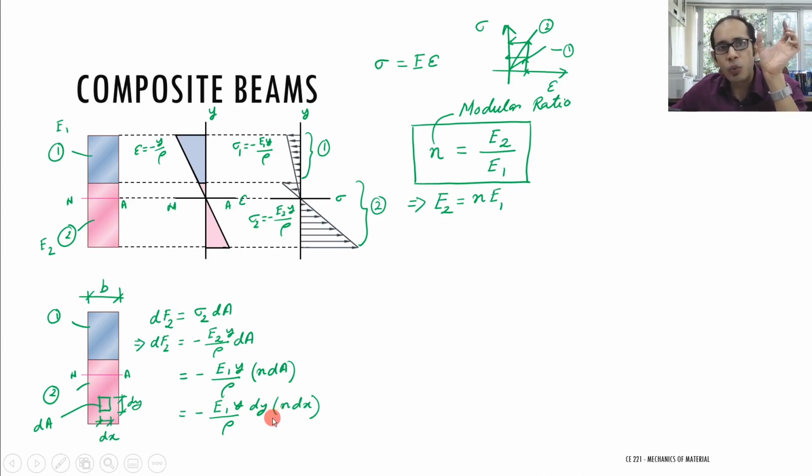Now why am I averse to increasing the height? Because I don't want the position of my neutral axis or the overall strain profile to change. I want it to have a strain over here, a zero strain where the neutral axis was, and a bottom strain over here. I don't want my strain profile to change. If my section suddenly becomes too wide, my strain profile might change. So I am not going to change my strain profile.